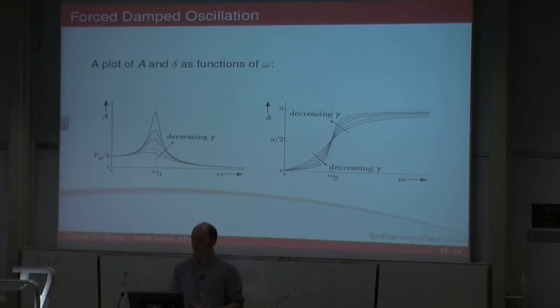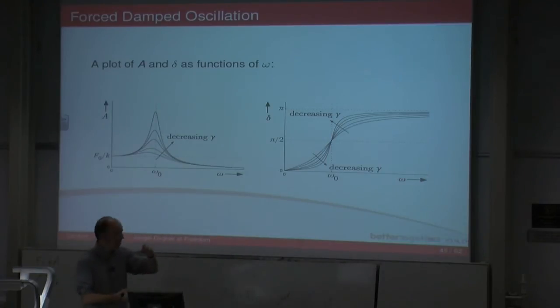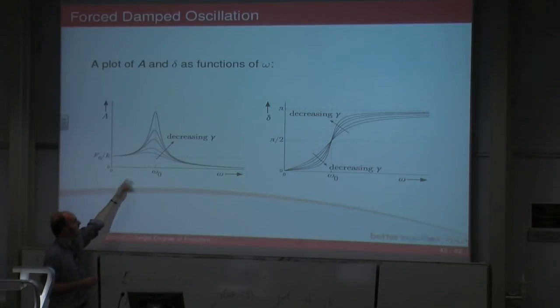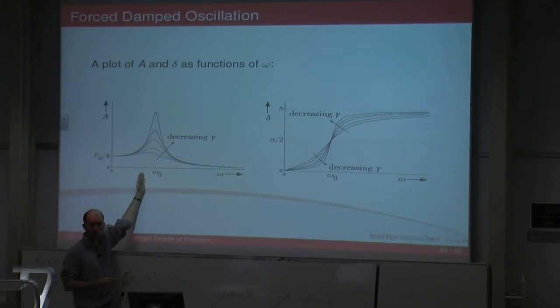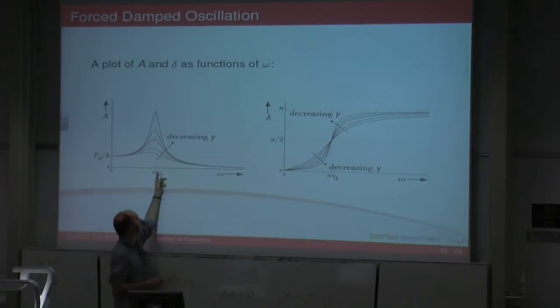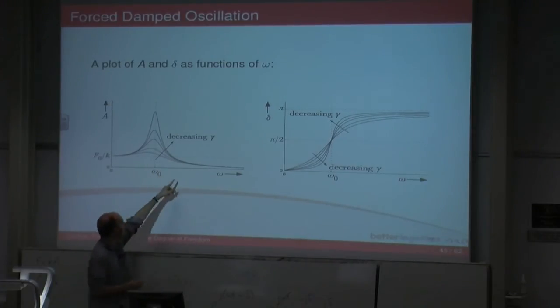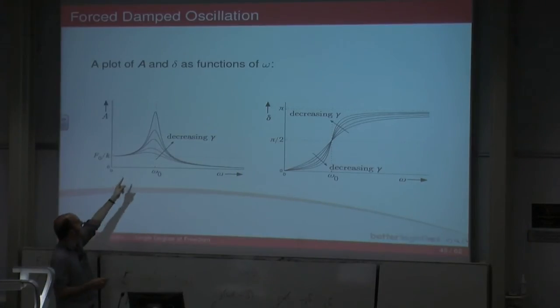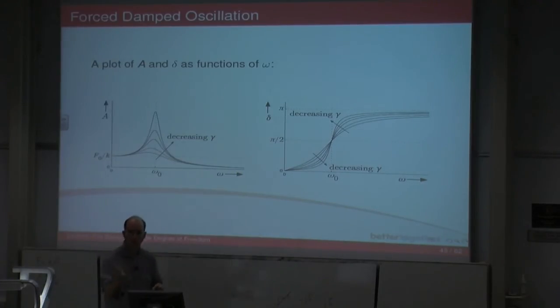And if you happen to be rotating it at the same frequency as the stiffness of that mounting bracket, the amplitude of that oscillation is going to increase massively because you're exciting at that. And so you don't want to operate it at that, you want to do it in this region or this region, but don't operate it in the middle. If you are aiming for this region, you want to get through there as quickly as possible because there will be some damping, and it can probably deal with a small time of it being at a peak amplitude, but not long.